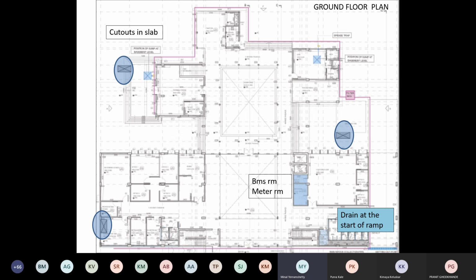But suppose your plinth is only 450. For whatever reason, you have a constriction. Suppose the entire building is done for handicap and there is a ramp issue, there is no space, and 450 is also high, a problem. Okay, I'm just creating a scenario for you to understand. Now in that 450, the size of the beam is 600 because there is a basement. Where will you get a proper window? Difficult, no? So in such a scenario, there is no window. Imagine that. Now in such a scenario, you will have to cut your slab internally.